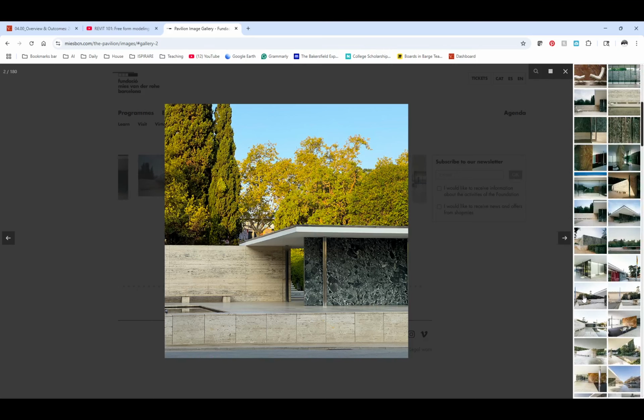And the reason why I'm asking is I'm not entirely sure it's travertine. Honestly, that would be a waste of material. It would probably be some sort of coping cap. When you build walls that have no roof above them, you put a coping cap on top of it, and I suspect that's what it is.